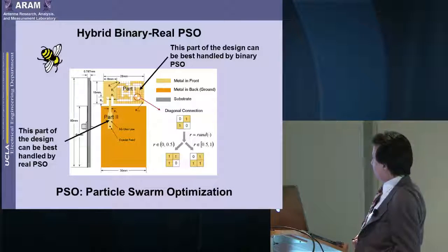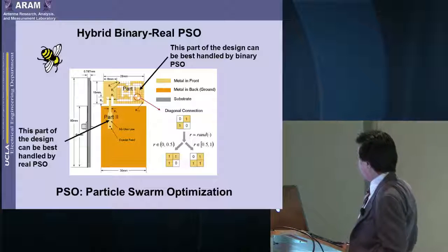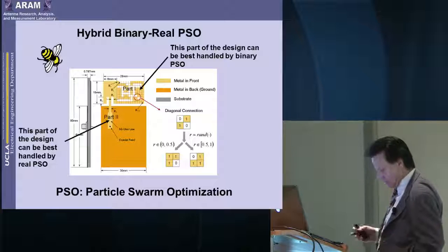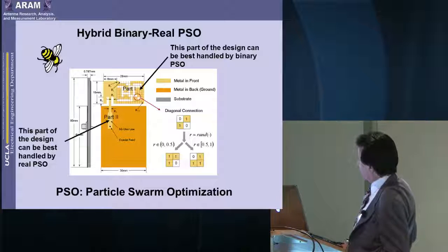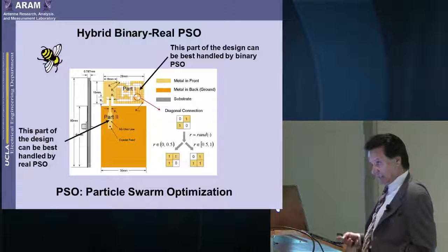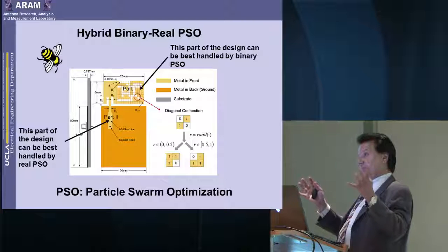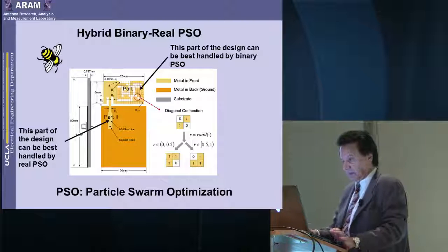We wanted optimization to give a design, albeit weird-looking shape antennas, in order to do a particular performance. So here we use a hybrid parameterization. We have a real number for this part, which attaches to the transmitter, receiver, or whatever, and we have a binary for the shape of the antenna. And collectively, this is an optimization over 100 parameters. 100 parameters, dimensional space that we are optimizing in order to get the best design for particular performance.